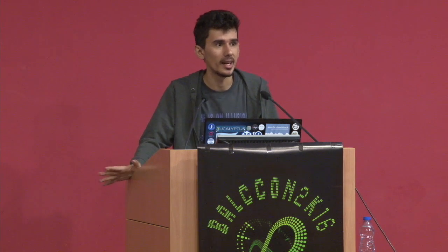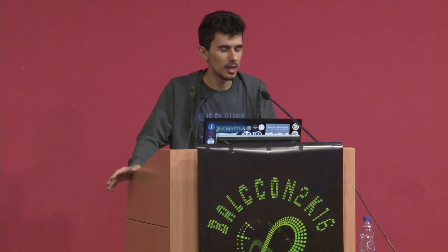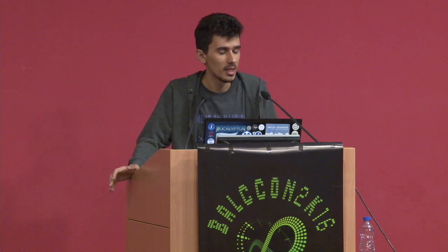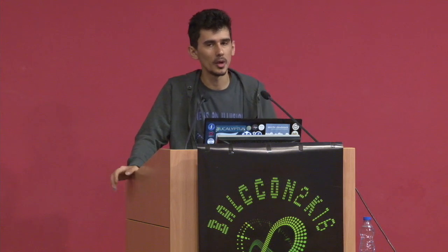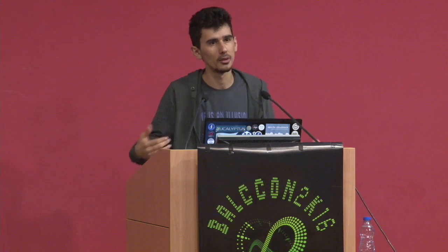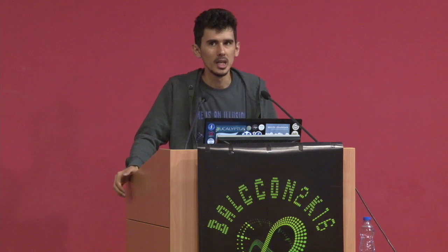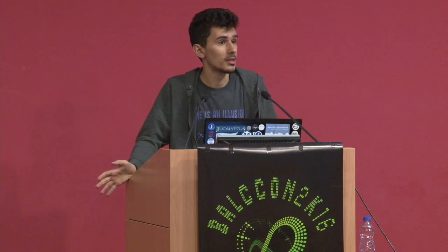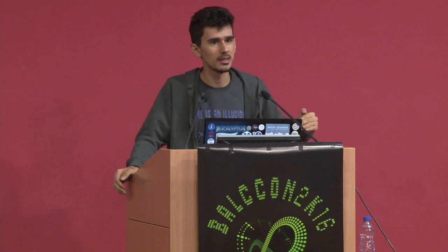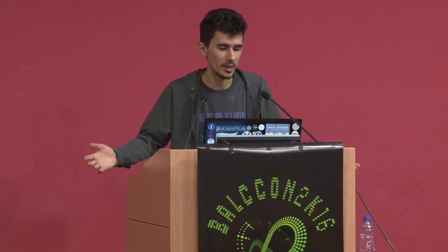Then you're going to need something extra. In this matter, I'm using I2C because it's really nice. Just two cables can be connected, and if my chip supports it, depending on your hardware, I can connect 10,000 motors in one device with the two cables. I just need to write the address list and I can control them, which is very nice.